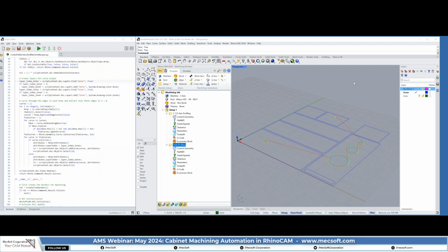Okay. One of them goes back to the actual nesting portion. The question was, could you have nested grouped curves, or does it have to be polysurfaces? No, you can nest grouped curves. There are a little bit of caveats. Joe, you want to mention them for nesting curves? Yeah, in the nesting module, you can select surfaces and or curves. You can't mix them both.